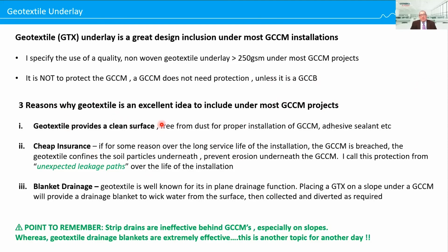The three reasons why geotextile is an excellent idea to include: firstly, the geotextile provides a clean surface free from dust for proper installation of the GCCM and adhesive sealant. The most important reason, and I call it the cheap insurance method, is that if for some reason over the long service life of the installation the GCCM is breached, the geotextile confines the soil particles and prevents them eroding underneath the GCCM. I call this protection from unexpected leakage paths over the life of the installation.